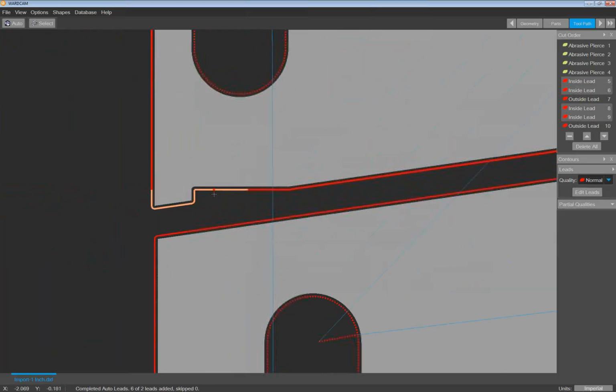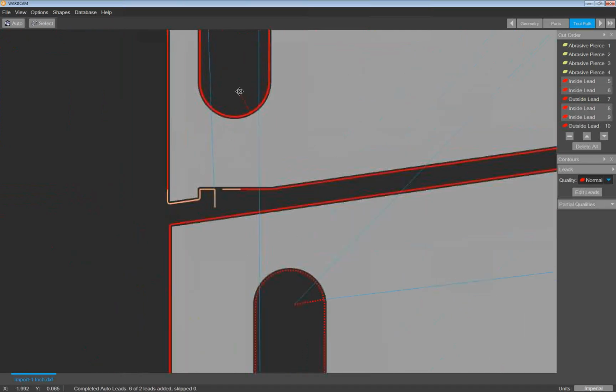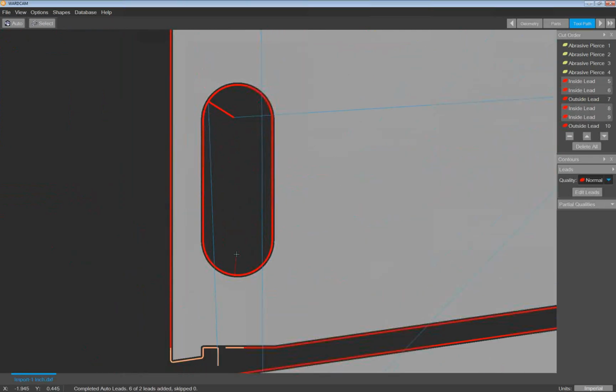And if I wanted this one down here also, I could do that. And then I'd probably want to change, anytime you start manually changing lead positions, you always want to make sure that you're not putting yourself into an area where you might get a collision. So if it finished cutting this slot here, if that slug tips up, I might cross right across there. So I can just move my mouse down again and just change that lead position.